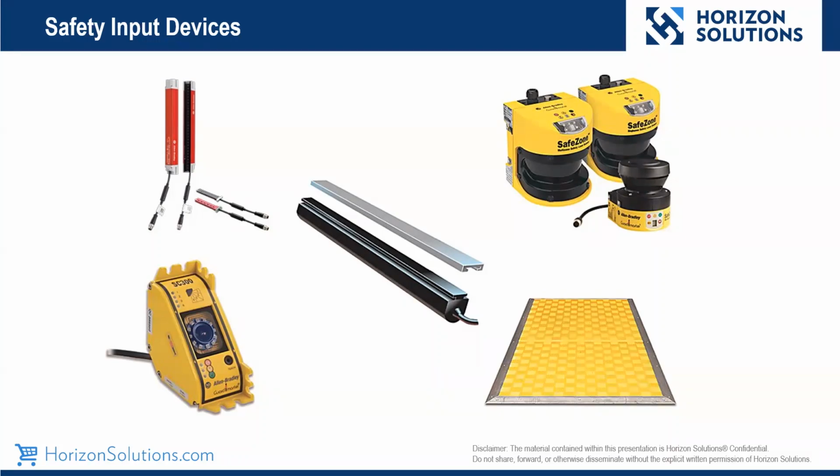So again, in this case, with a 14 millimeter object resolution on the light curtains, we have about a ½ inch depth of penetration. Whereas with a 70 millimeter area scanner, if we're doing leg detection, we may have up to a 3-foot depth of penetration factor based on the arm span of that person.